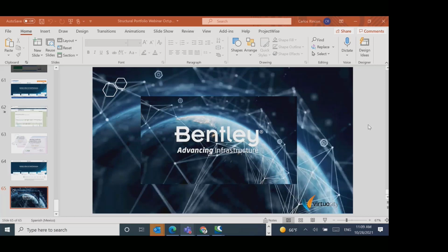It's so different, so quick, because the commands are more focused. STAAD.Pro includes a wizard for bridges just for the line part, but OpenBridge includes all the information on substructure and superstructure together at the same time. In 5 minutes you have the whole model, and in 5 minutes or a few more you have all the loads, including the AASHTO standard. So you save time very well because it's more focused software.